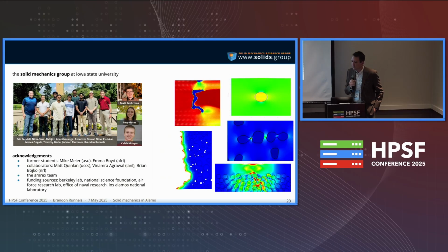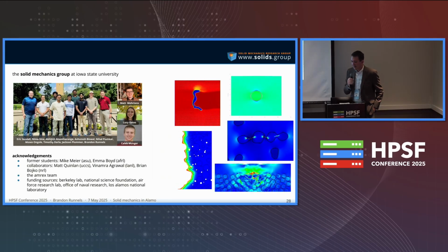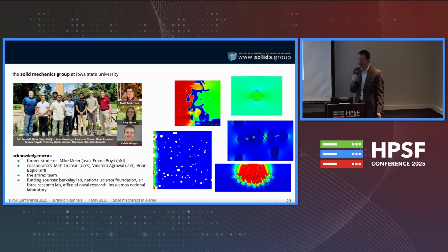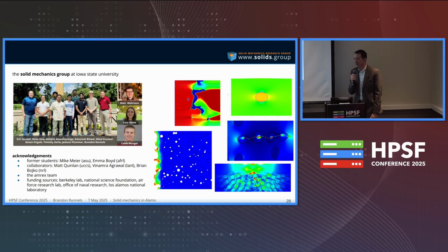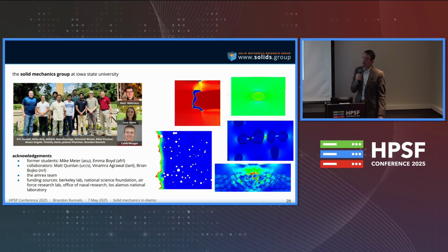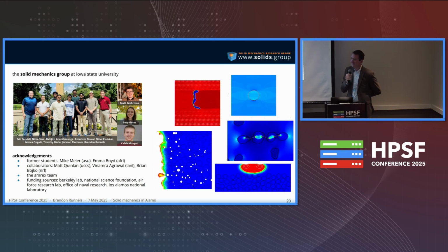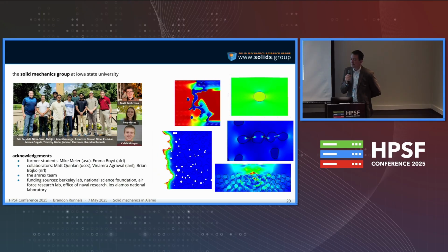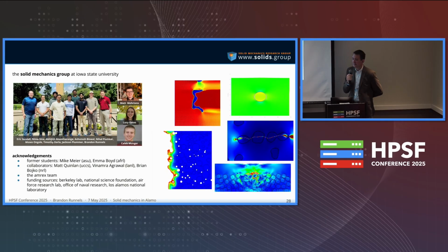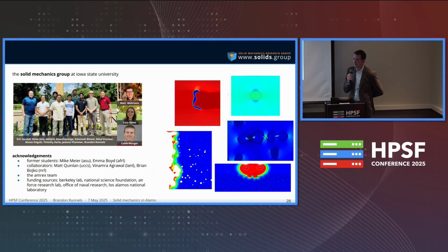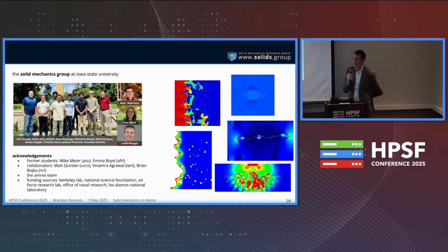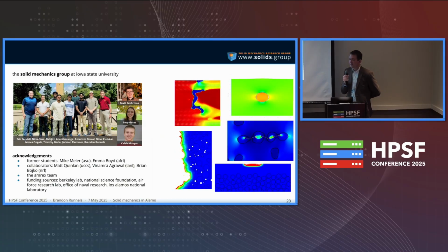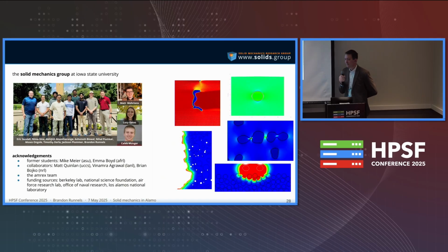What about metal casting? Are you looking at that problem? No. There's no reason why we wouldn't. It just isn't one of our priorities right now. But we could. Well, I'm saying that because I have been developing metal casting simulations using AMReX, but what we're missing is how, once the metal solidifies, we can model entrainment of metal oxide into the solid, but when the solidification happens, you start seeing metal oxide cracks, and that's the capability we don't have.